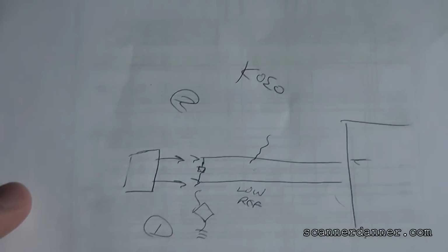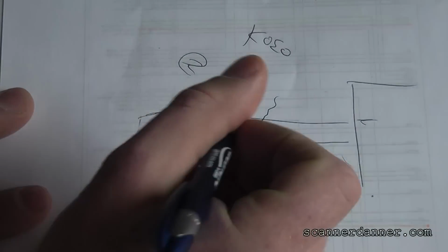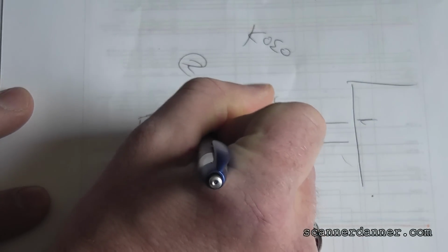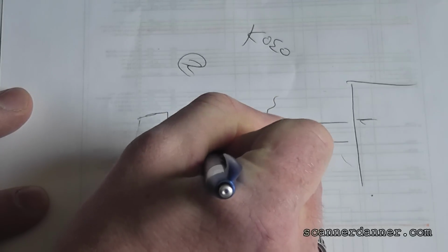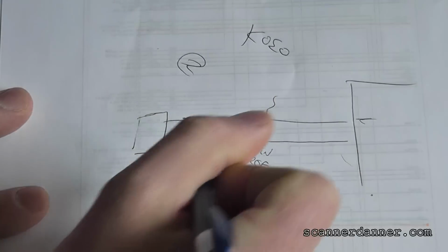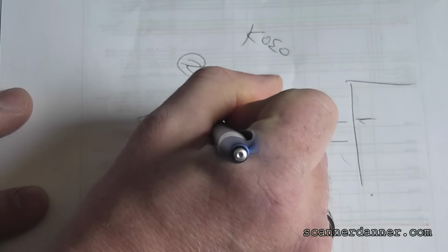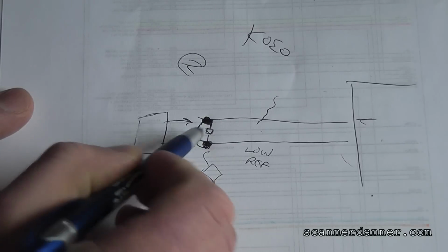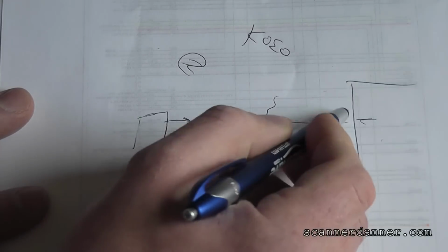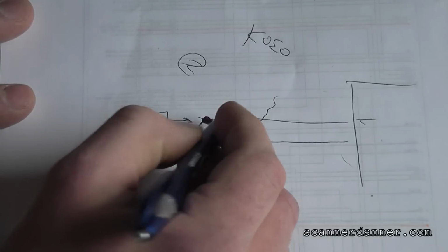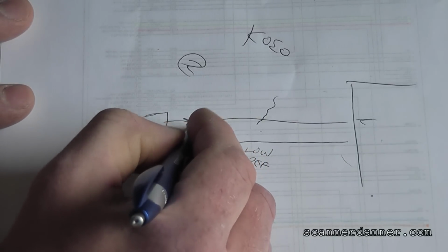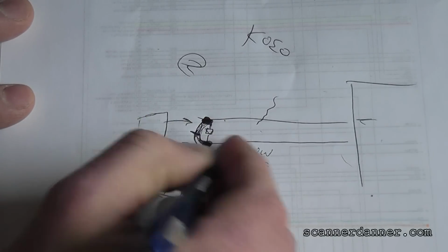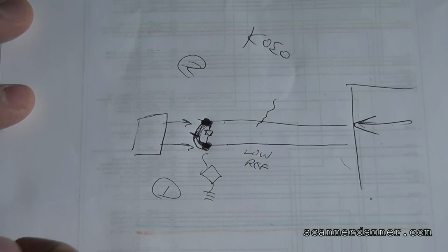Guys, listen, that is crazy. What they want us to do in this flowchart is to take a fused jumper wire from here to here, okay? So you got a fuse in the middle, the 3 amp fuse, which is not going to be in place to protect the computer. That's going to be in place in case there's a short in the circuit so we don't burn up the harness. So we're taking a jumper wire from the control to ground and we're commanding the driver to turn on.